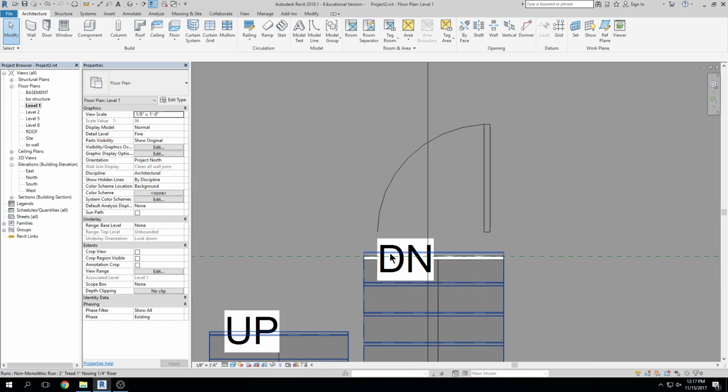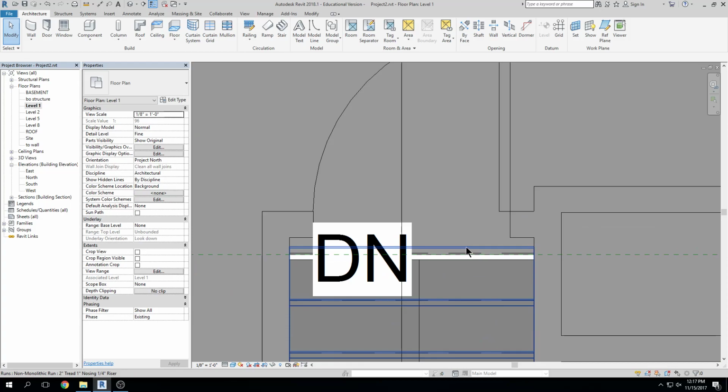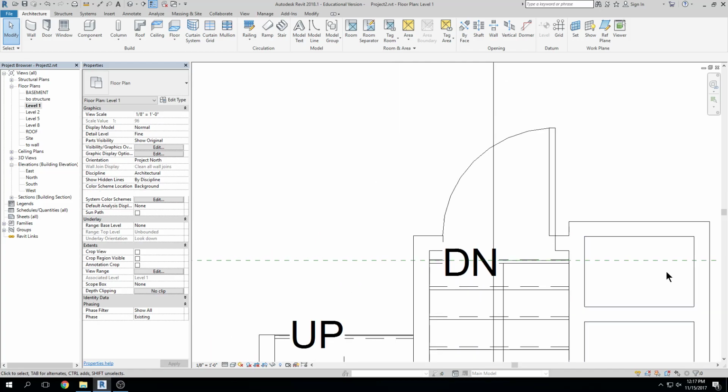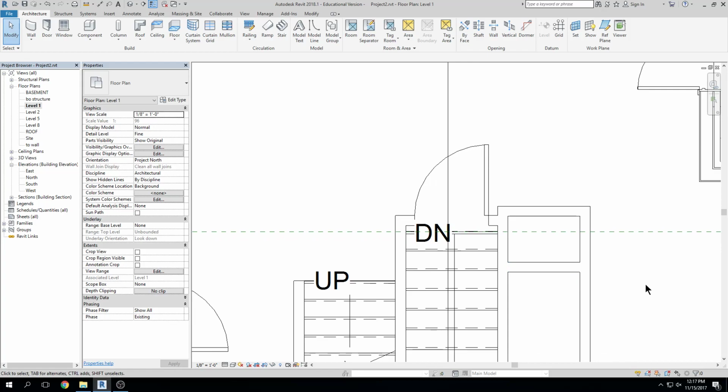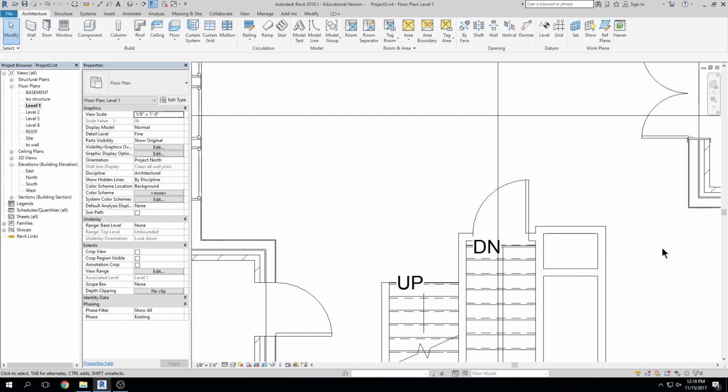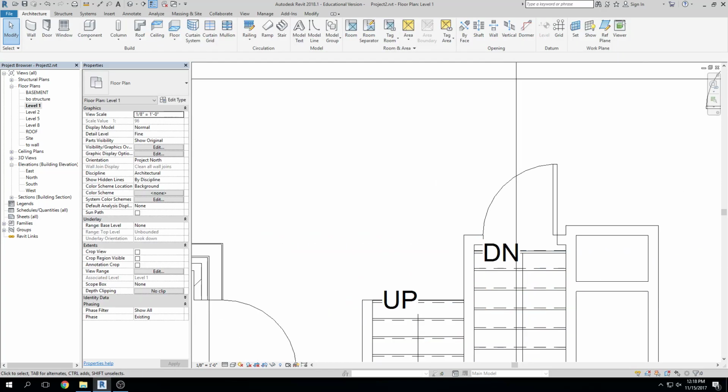This right here looks weird in shaded view, right? You see it looks like there's a gap. There's not really. And if I go to HL, hidden line, I don't see that. I just see the edge of the tread coming out. Right? Does that make sense? The lining up is tricky, so I'm not saying it's not, but the easiest way to get it is to go into section and then to draw a reference plane.